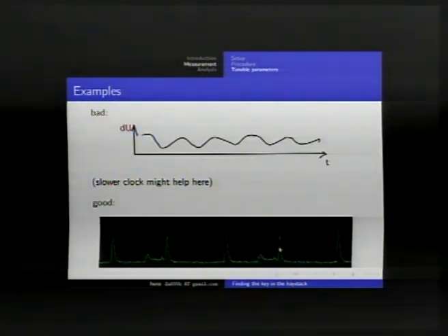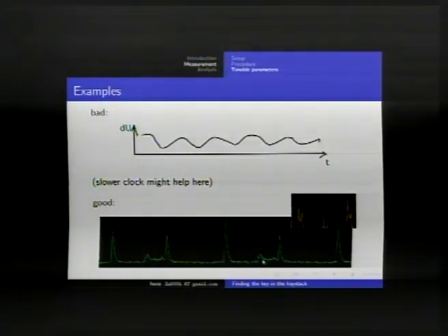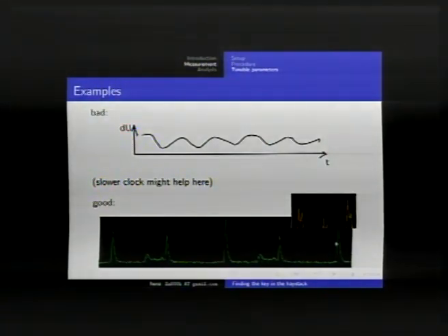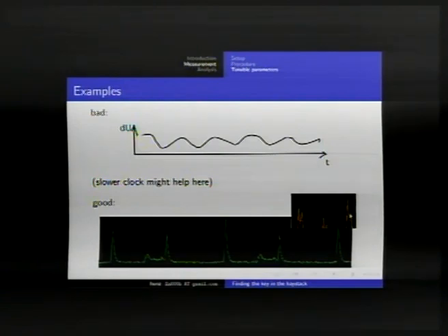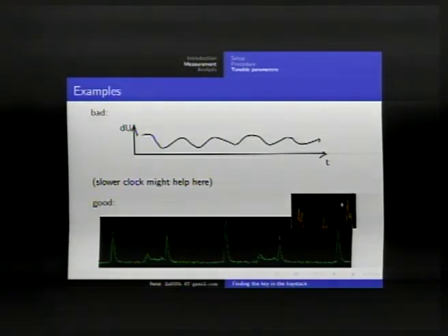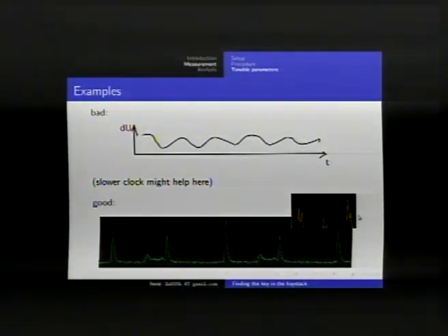It's an 8-bit AVR microcontroller. And here we have a rising clock edge. Oh, it's not shown here. This is the power trace. And here falling edge, rising edge, and so on. Don't ask me what this bump is. I have no idea. Here we have two different power traces. With different plain texts, one can see that they differ hardly.